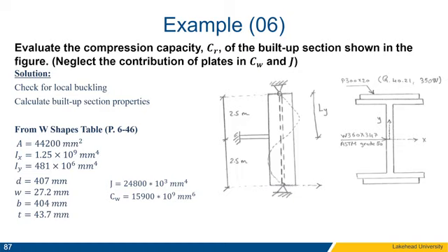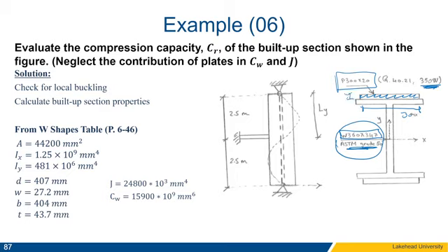Also, we mentioned here that the section itself is made of grade 50, and we are given the specific section for that I-beam, while the plates themselves are made of 350W grade steel, and we are given the dimensions of the plate. So when it is mentioned 300 by 20, it is obvious that this dimension is 300 and that thickness is 20 millimeters. Okay?